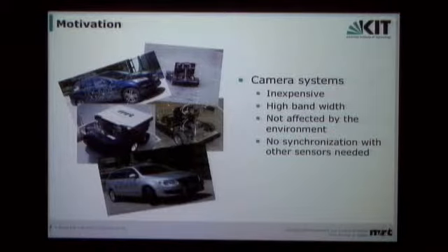And one last point that I would like to stress here is that if the image processing is also used for the environmental perception, then it is sometimes difficult to align the ego motion from an external sensor with the camera data, so problems with timestamps and everything may occur. And if the vehicle ego motion is computed entirely from the camera, then there are no synchronization issues.